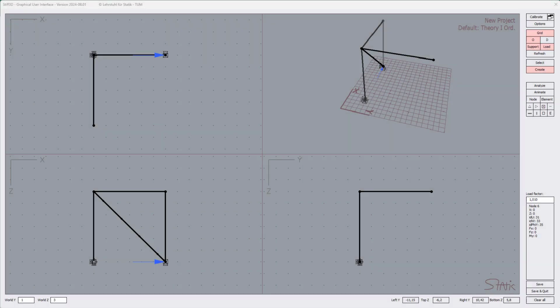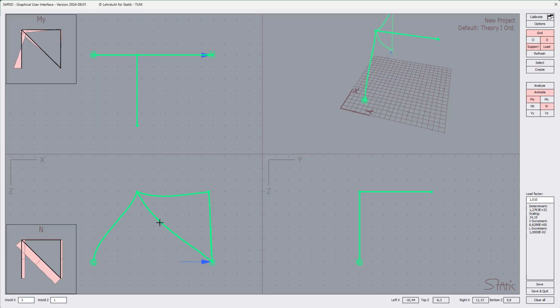Next, I would like to show you how to create other kinds of hinges, in particular with respect to longitudinal degrees of freedom, and also with respect to an inclined member, just like this diagonal for this little modified structure. We have this diagonal, we have this additional column, and you see here we have a roller support. That means if we do the analysis, you see this node is moving to the right, and as a consequence we have here the diagonal tensile normal force.